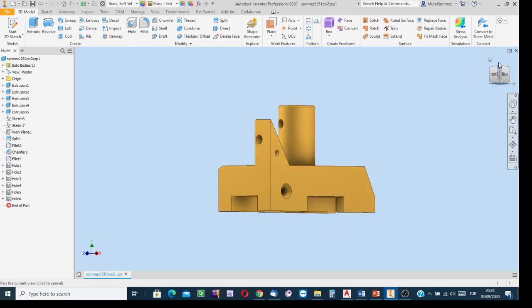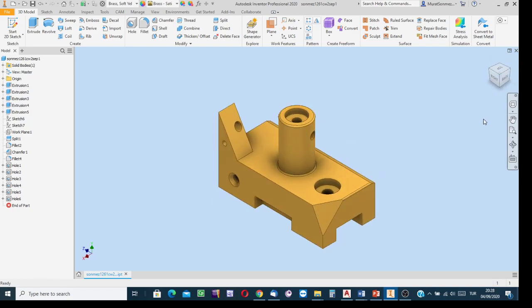Okay, after reminding you of such basic definitions, front, top, left, right, back, when saying width, what do we mean? If someone simply says width, this means the width of the object. But if the width is the size of a feature, then it should be mentioned. For instance, say the width of this triangular prismatic feature, the width of this cylindrical feature, the width of this channel. But here, saying width is considered as the width of the object.